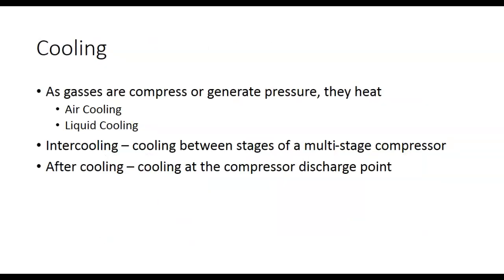Cooling. We have to cool when we compress these things. When you compress air, it's going to heat up on you. So that means normally, especially in big shop compressors, we're going to have some way to cool it down. Another problem we have with gases is that just about all gases, especially air, have a lot of moisture content in them, right? And air can only hold so much per cubic foot.